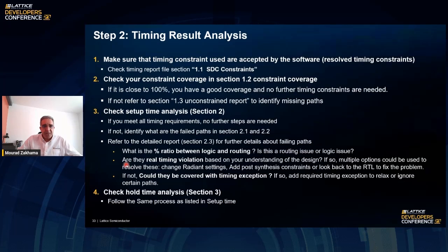And once you do that, based on your understanding of the design, are we talking about a real timing violation, or is this an expected timing violation, meaning that you have a clock domain crossing, for instance, but you covered that by design? At that point, you may add a timing exception to tell the software or the STA tool: don't look at this path, you don't need to analyze that path, I covered that by design.